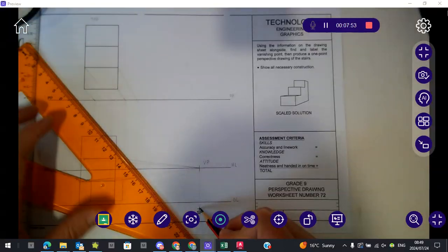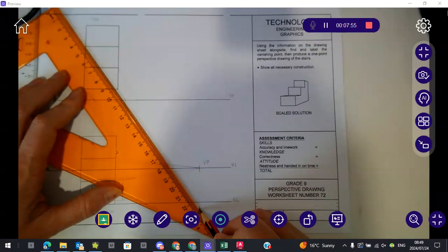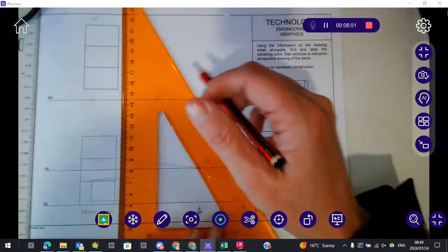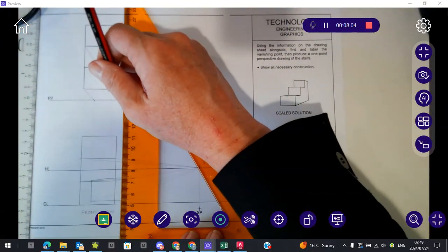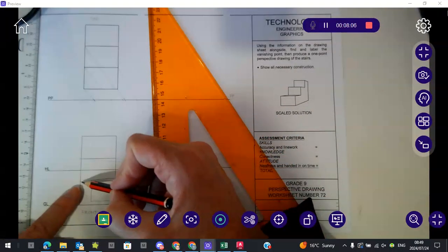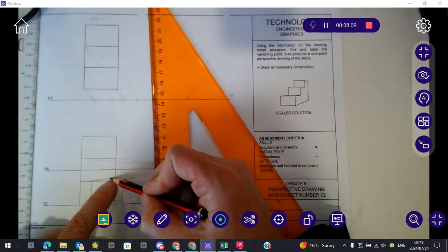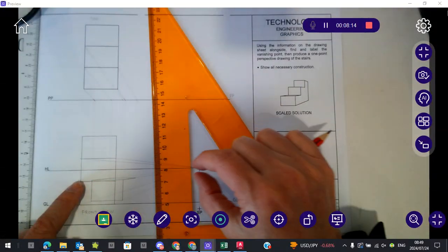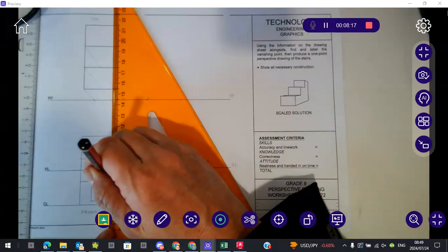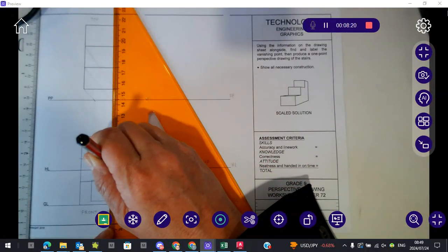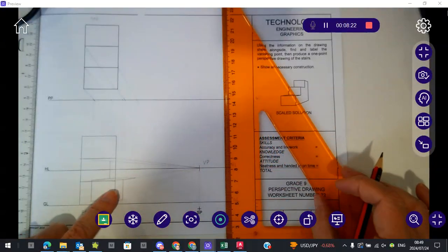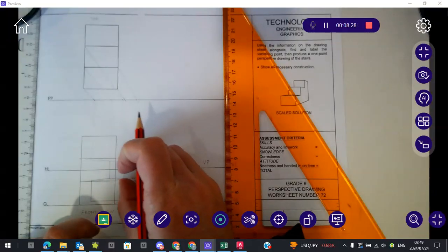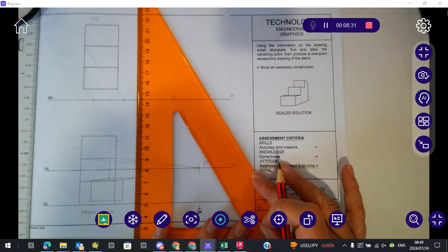I go to my top view and I say, right, where is this stair going to go to? This is going to give me my depth. So I can take my height so far, and I know that my height is going to go to there because this line joins this line here. And as they reduce there, I can see that that is where I take that height to there. I can do the same on this side here. I can see that this gives me the height for that stair there, and I can draw this line up.